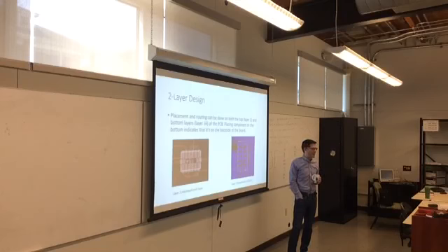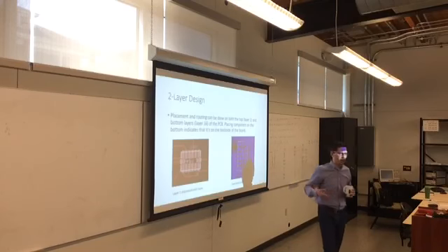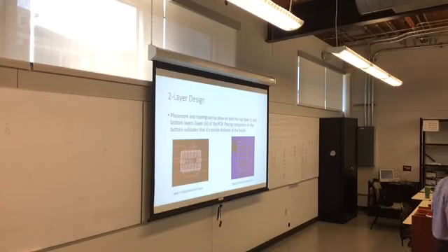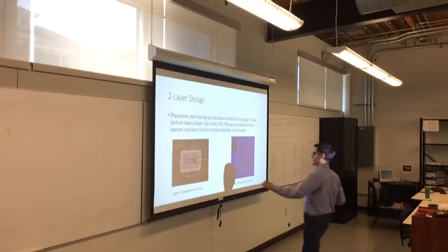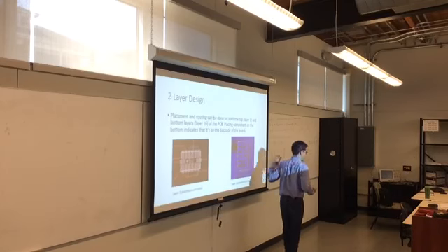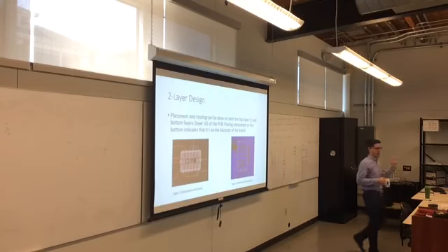Like the silk screen is, what, layer 40 or 50? It's something like hundreds of different layers in each. Right, there's a bunch of different layers, and so when you go to the manufacturer, they have to understand what layers are. Like the silk screen's made layer 50. Why is it layer 50? I don't know, there's probably some rationale. But it's just on a different layer. So this is a layer 1 placement, this is a layer 16 placement, which is essentially the bottom of the board.